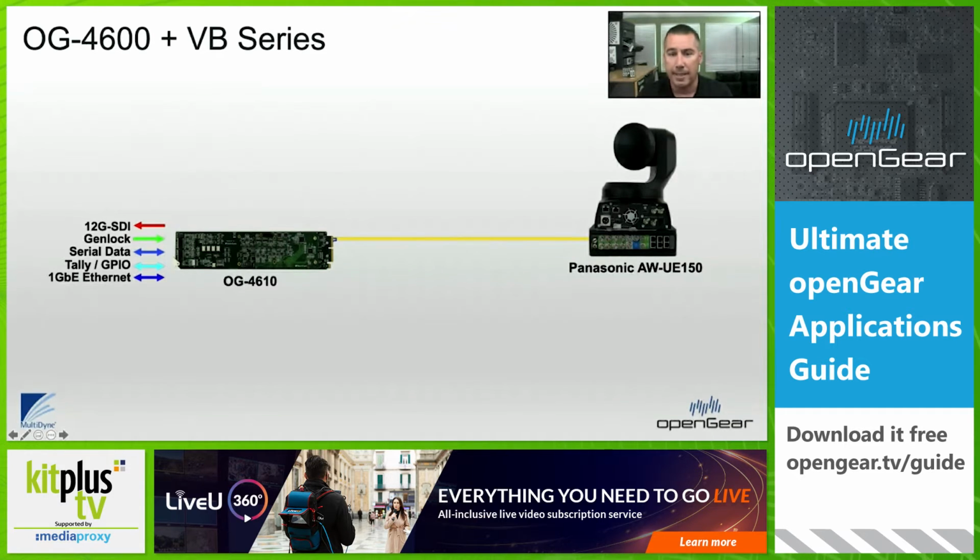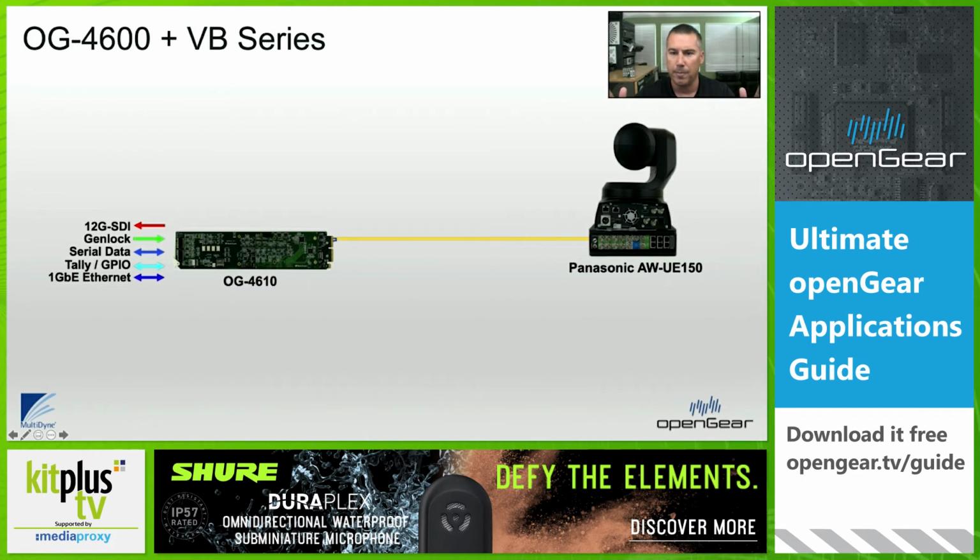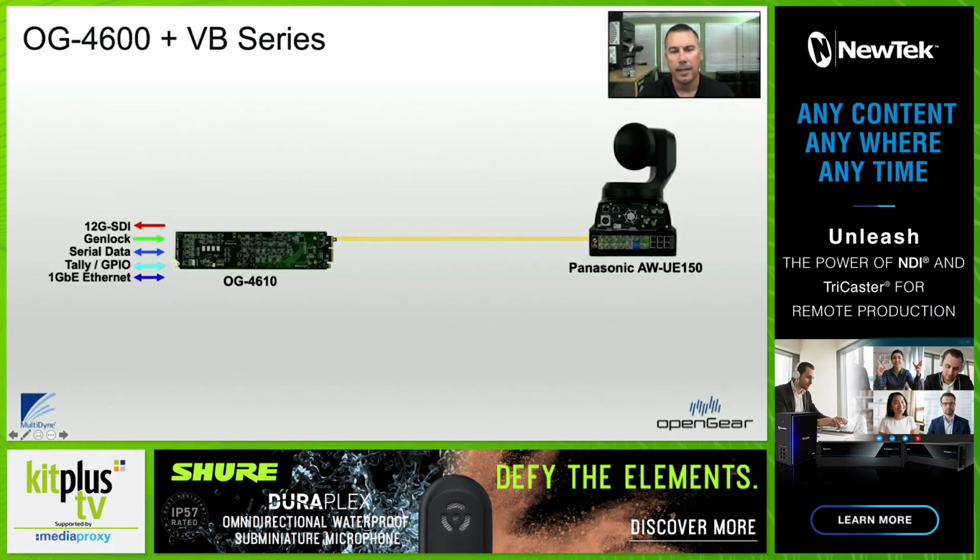And for this application for PTZ, we have a new rear module that is standard width, which is 2 slots in the openGear platform out of 20. So you can get 10 of these cards in a 2RU frame. And in the rack room, you get all of the benefits of openGear when it comes to dashboard control and monitoring. You get redundant power, additional cooling capacity.